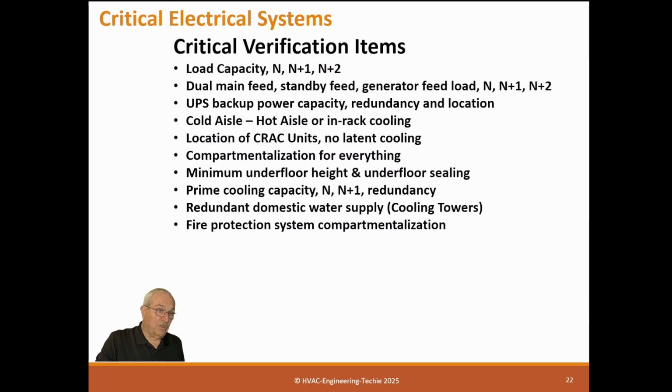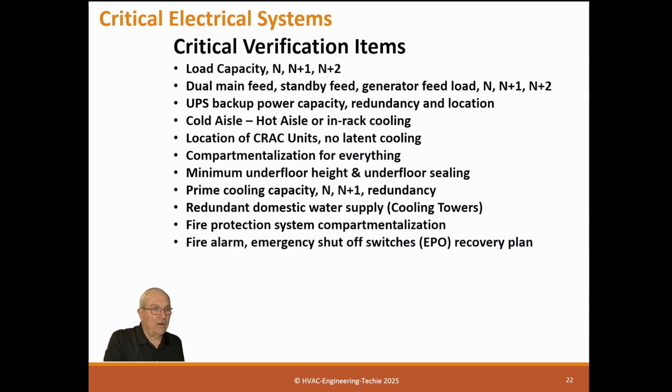When you go through the fire protection sessions, you'll understand that these critical systems normally have two fire protection systems. One is a gas system to protect the data, and another is a sprinkler system to protect the structure. If the structure is getting ready to burn down, it's way too late for the data, so you can pour water on it, not a problem. Fire alarm, emergency shut-off switches, EPOs, and a recovery plan.